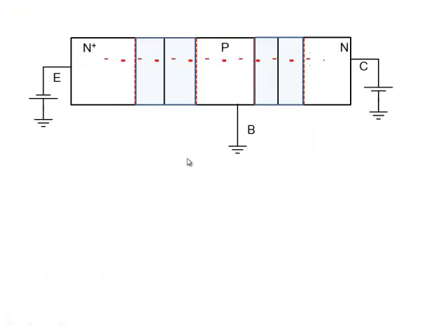All right, let's continue and see this here. So if I neglect that small number of carriers that recombine in the base, I can say, as a first order approximation, the current in electrons injected from N plus, all that they do is they go all the way into the collector. And this is the whole current here.